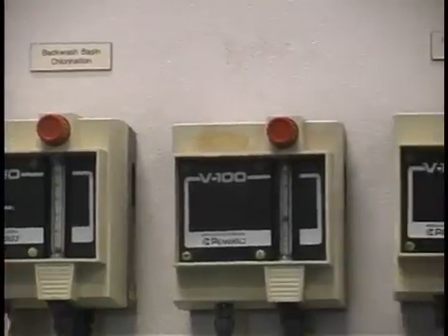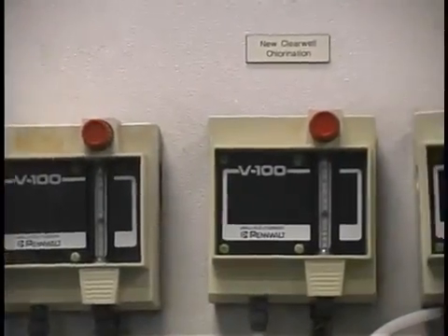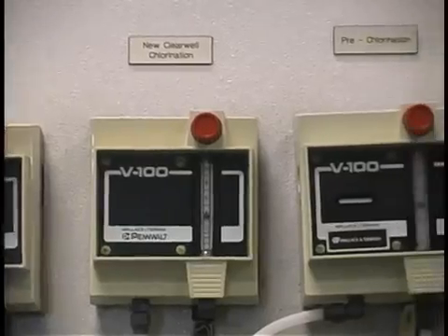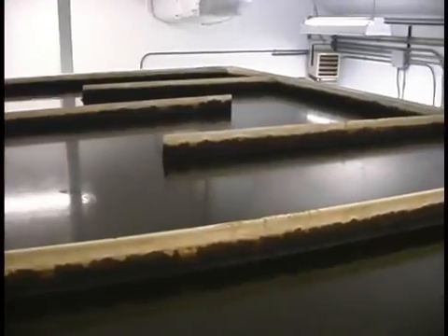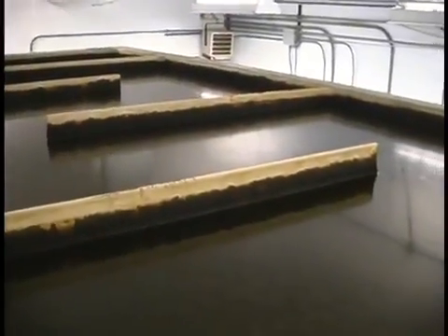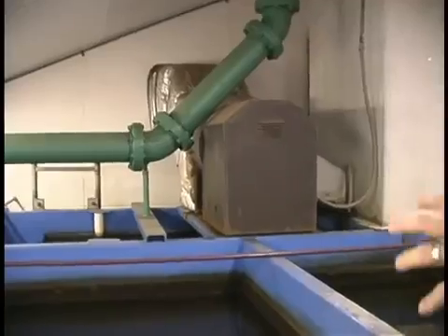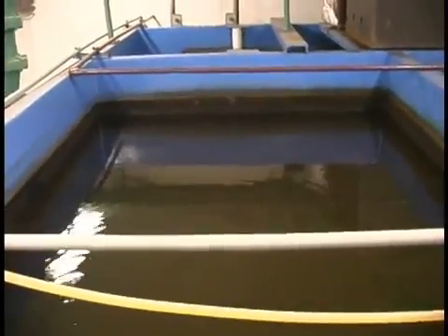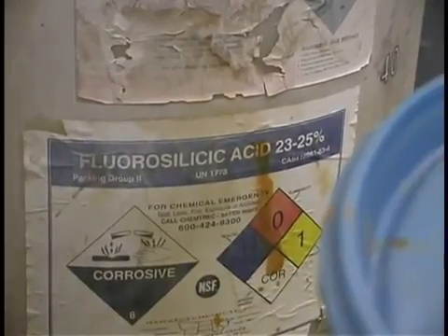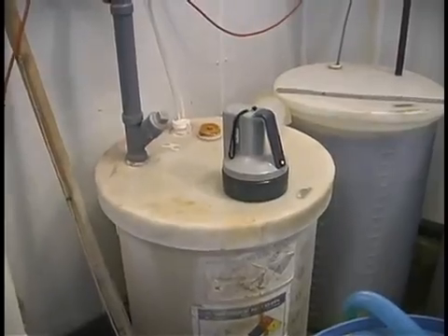Chlorination with gas chlorine for biological growth control on the filters and oxidation of the iron in the raw water. 1 hour detention time to facilitate the iron oxidation. Gravity filtration through 24 inches of anthracite. Post-chlorination prior to storage in a clear well and fluoridation before being pumped to the distribution system.